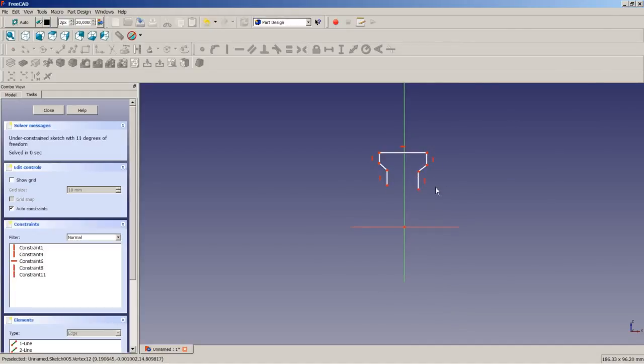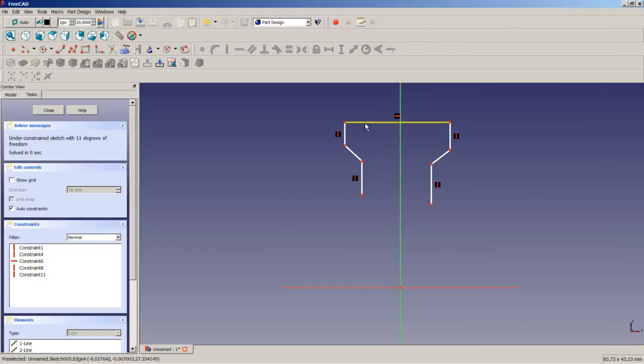I'm creating some sort of upper head on this pocket to make sure that I get some overlapping of the bodies. If I would just have reused the sketch once more for the pocket, I wouldn't have got overlapping, and that would have resulted in an invalid sketch.